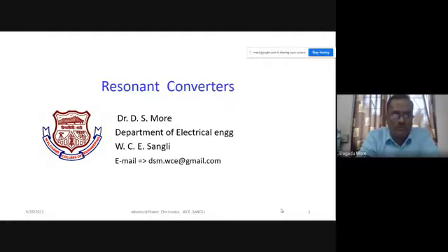We have to go for multi-level inverters whenever the output requirement, particularly for motors, induction motors, may be 3 kV, 3.3 kV, or 6.6 kV. And for this, if you want variable speed, we require an inverter. Under those medium voltage conditions, we require the inverter topology, that is the multi-level inverters.